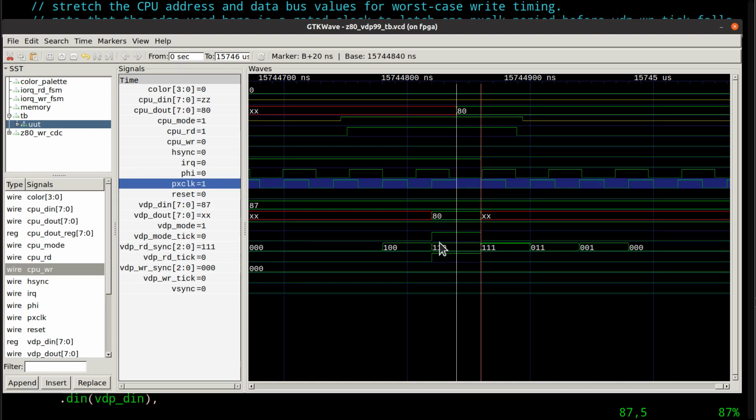And when I say it's ready, we can do that anyway, because I know that the setup time when we read the registers that are implemented inside the FPGA will be stable by this time, because I know that the period of pix clock is many nanoseconds long, all right? I mean, it's this, oops, I keep doing that.